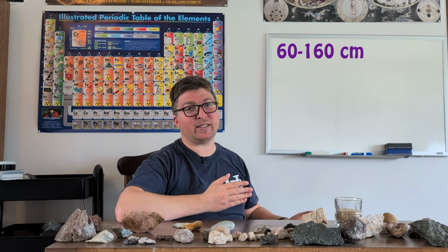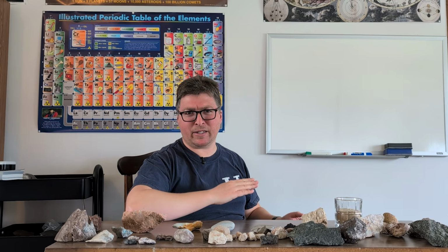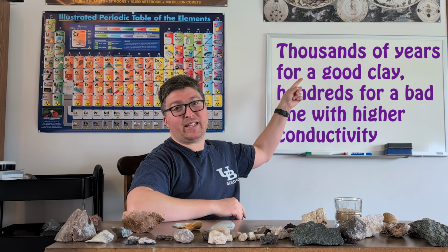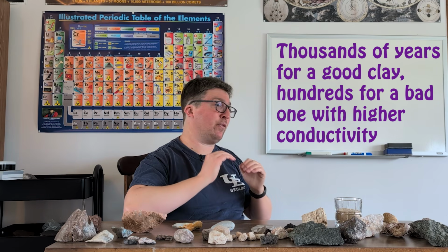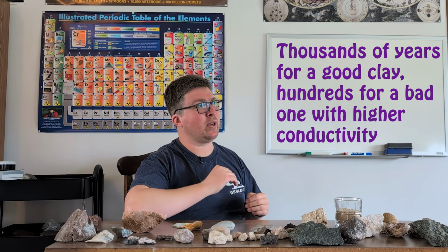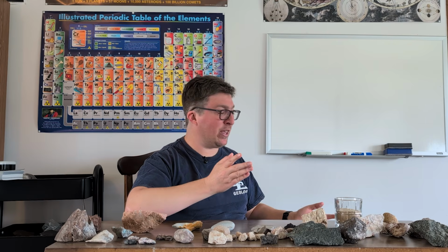So how long does it take for contaminated, nasty landfill water to penetrate through the clay and make it into the groundwater? I can't do that math in my head, but I'll do it later during editing, and there it is. So if the landfill is well built, there's no chance of contaminated groundwater making it through during any of our lifetimes. Now, of course, not all landfills are well built. I know that from experience. I've actually mapped groundwater contamination plumes from leaking landfills.